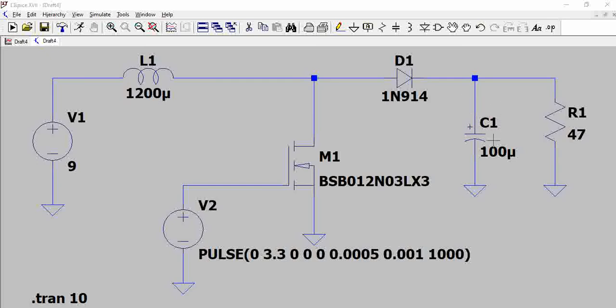And this particular capacitor is very important because, as we said, when the MOSFET is on, that means at the very initial condition when the power is on, the inductor gets charged, and when this MOSFET is off, the capacitor gets charged, and again in the next cycle, when the MOSFET is on, the entire current flows through this MOSFET.